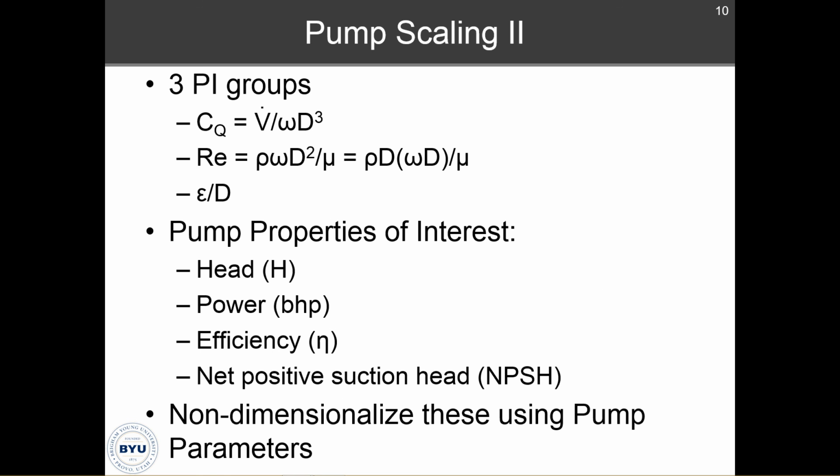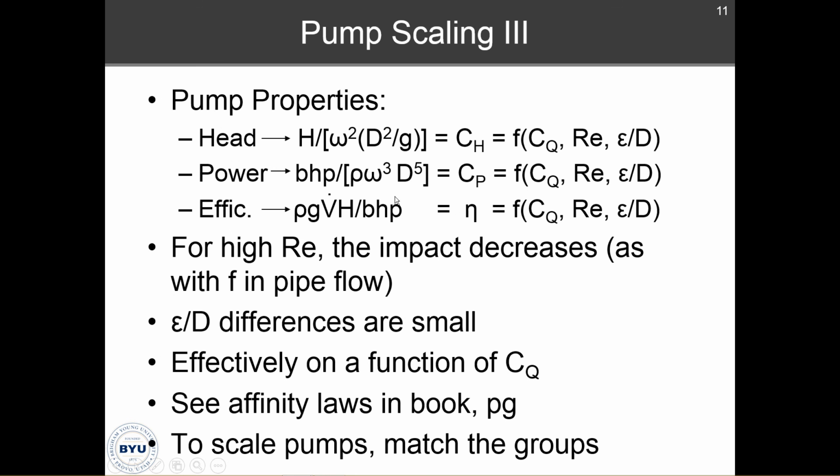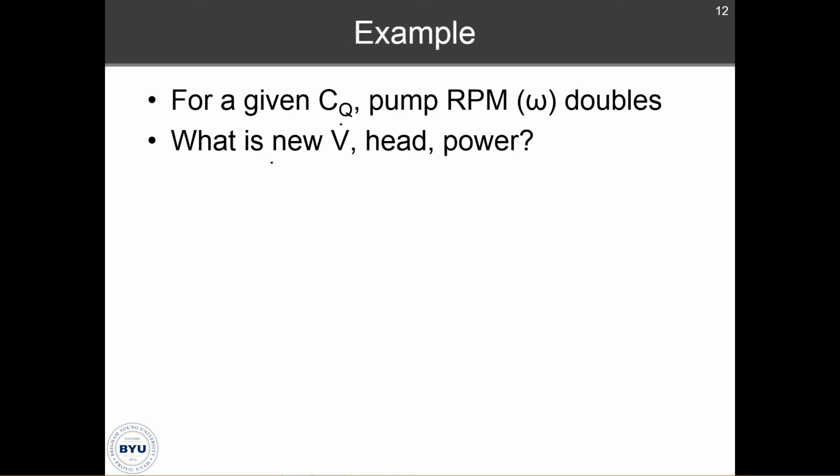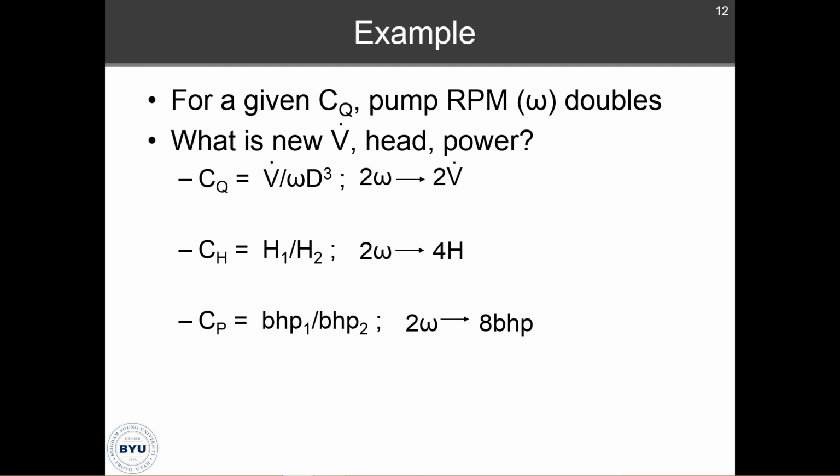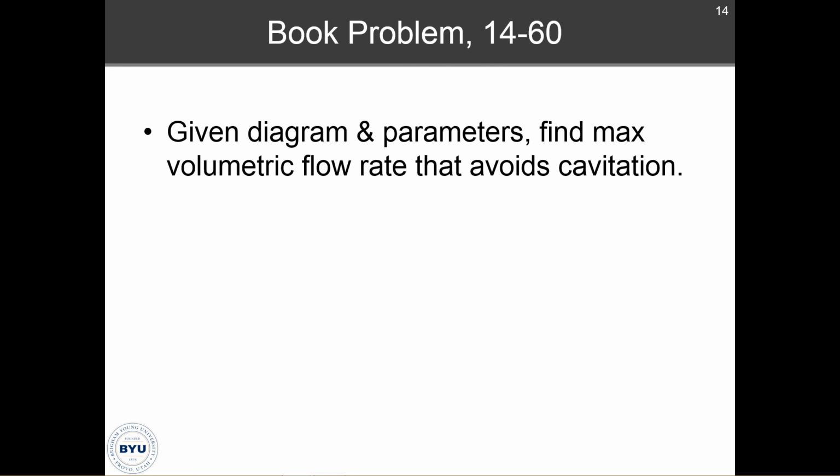Make sure you understand pump scaling, how to use these dimensionless numbers here, head, power, and efficiency, or in other words, CH, CP, and eta, which you've already had experience with, but it's defined again here for clarity. Make sure you understand how these work and how you keep them the same to maintain pump operation and pump performance when you're scaling to different systems. Okay. Finally, we can go through the book problem.